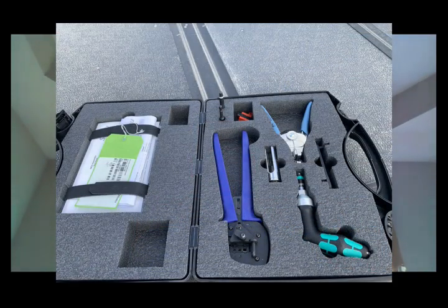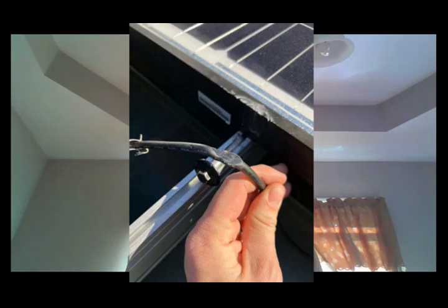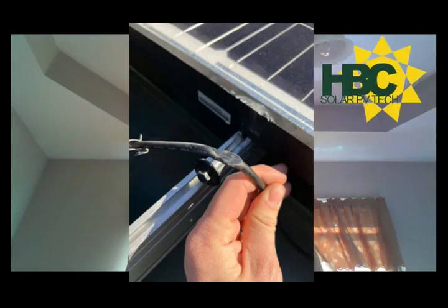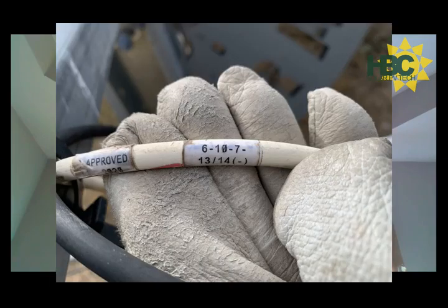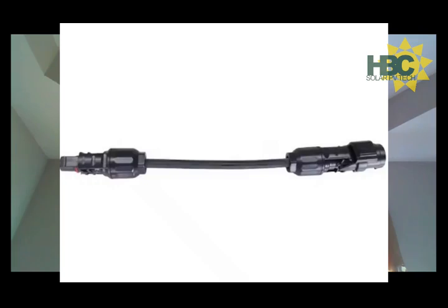How to repair ground faults in PV systems. Once you've found the ground fault, you have several options for repairing it. If the damaged conductor is in conduit or free air, you can replace it with a new undamaged conductor. A single conductor in a conduit with other conductors may be challenging to replace without removing all conductors from the conduit. If you find minor damage on a PV string circuit in free air, you can cut out the damaged wire section and replace it with a field installed quick connector like an MC4.